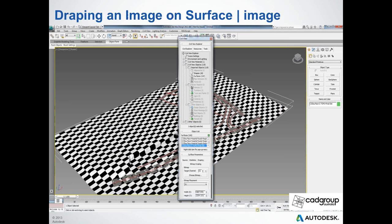So these are one of the simple tools where you can actually drape your photographic images over the topography in your model. You can bring in all this data, and then you can get your aerial information and place this over the model. So you don't need to manually texture everything or do things in 3ds Max Design. You can pick up these surfaces and use the Civil View Explorer tool to drape imagery over those surfaces. You can see here you can choose the bitmap, and you can place it to match the topographical information in that 3ds Max Design environment.